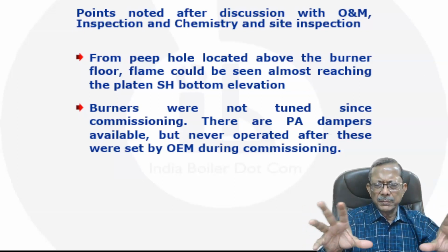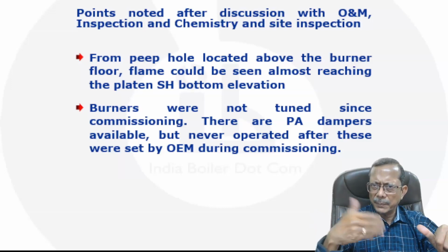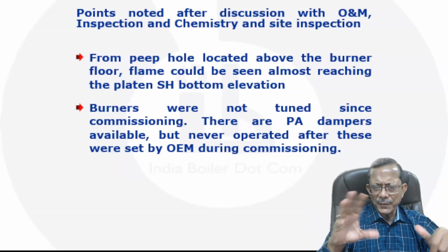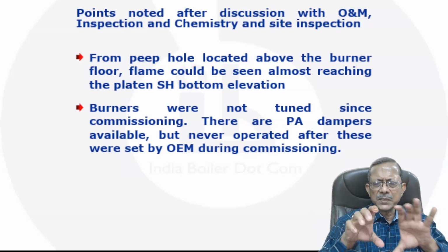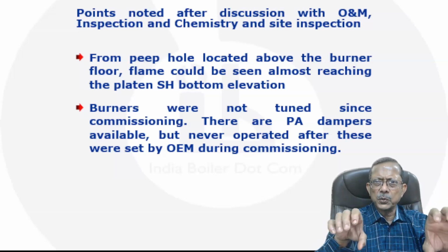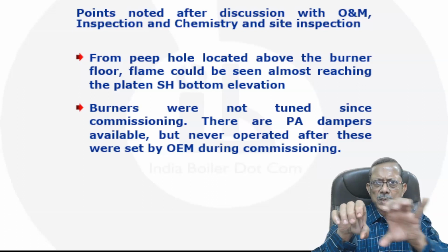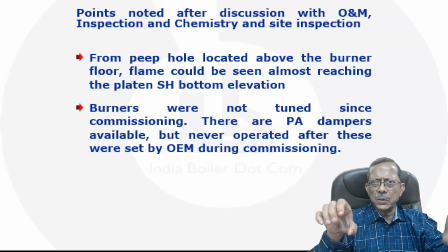There was a damper, which was actually a primary damper. Since the boiler was stopped at the time, I went inside and checked that if I move this damper, there is a sleeve and a slotted cylindrical portion at the core of the burner, and this sleeve moves over the slots and opens the slots one after another.